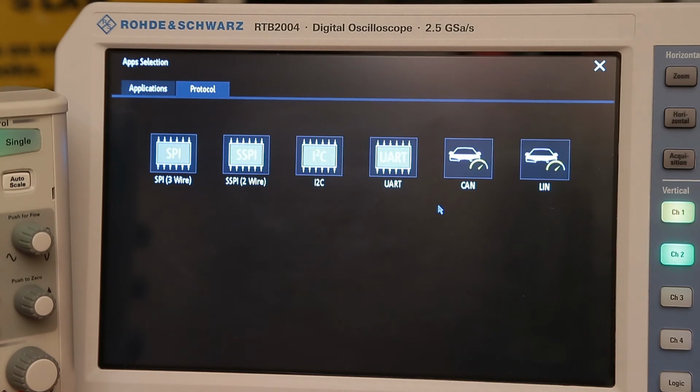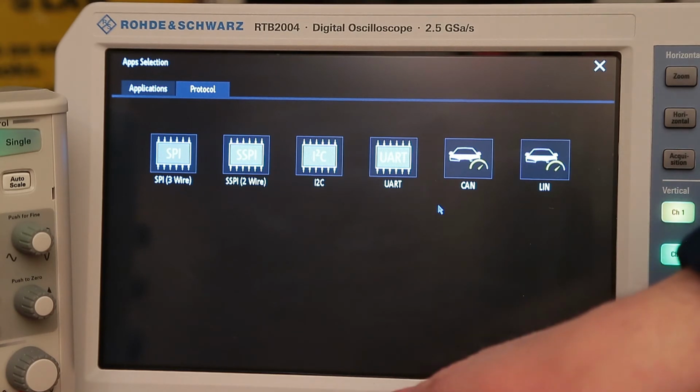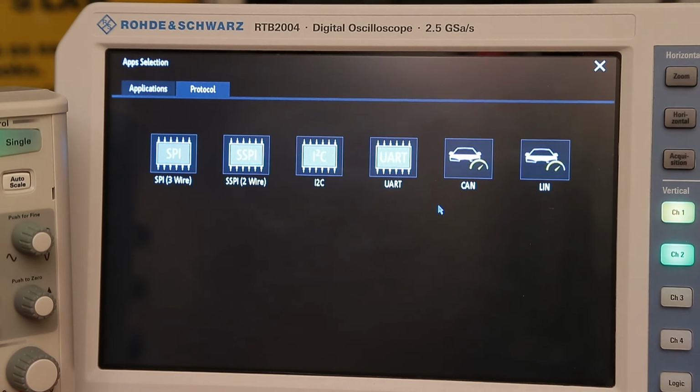another device to bring in signals for testing purposes, which is National Instruments, sorry, because the name just escaped me for a moment. It's a National Instruments myRIO, which is an FPGA development system that's driven by LabVIEW, and I've been generating digital switching signals up to 50 megahertz, plus I've also been sending out CAN bus signals, which it can generate. I was using one decode for the CAN, and I was also using the digital lines, using the pods down here at 50 megahertz, and the scope was quite happy to do 2 protocol decodes at the same time without slowing down, and I didn't have any problems.